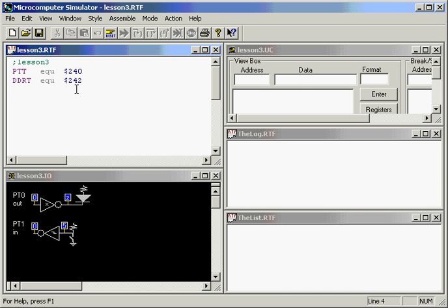Okay. I have no variables in this case, so I'll begin by defining my program here in ROM. And ROM on the 9S12 exists at 4000. And I'll begin at label main. The first thing I'm going to do is set the direction register. Now a value of 1 in the direction register specifies that pin is an output, and the value 0 specifies input.